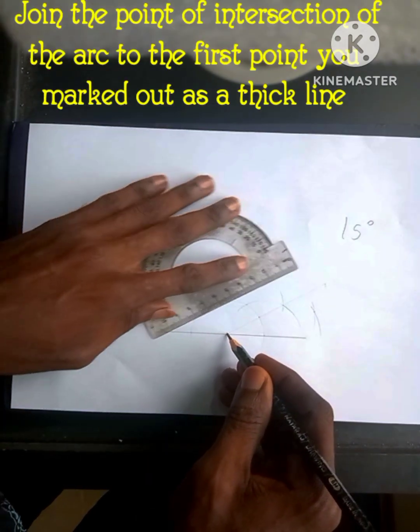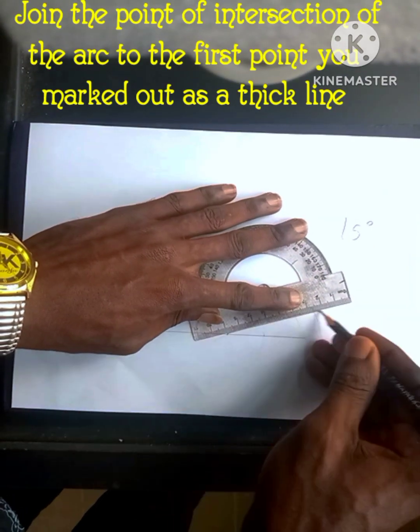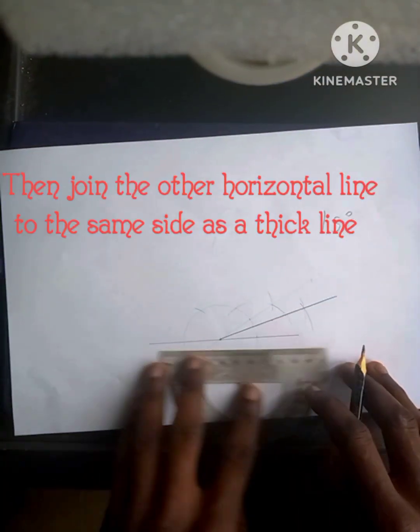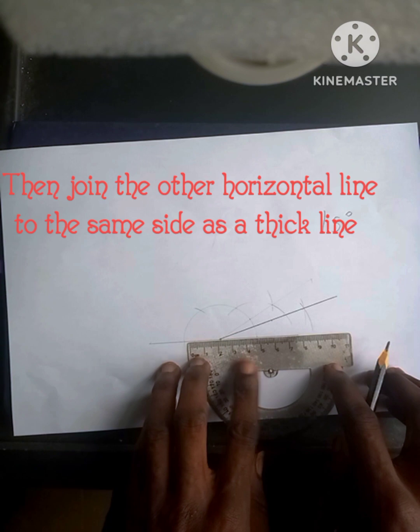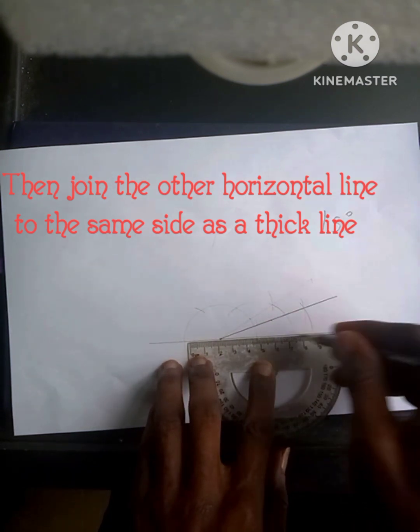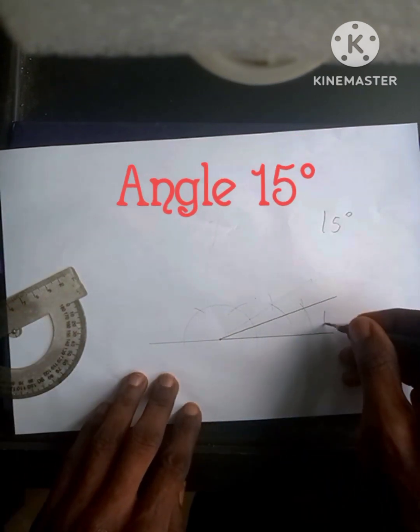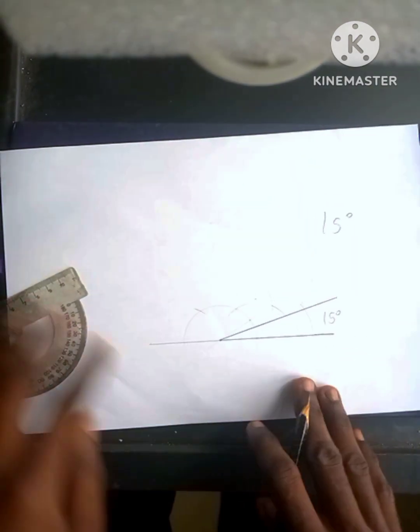When the two intersect, join it to the center point. That gives you the line for 15. Then join the horizontal line also. So that angle we got there is 15 degrees.